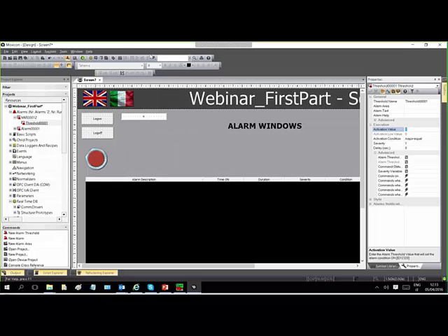The third way to generate the alarm, I'm using different colors to differentiate the ways. The last way could be, and sometimes customers are requiring, I have a new tag 17. I have an alarm that could be an alarm template, alarm 2, where I add just the activation minimum condition, activation value. Now I associate this alarm as a template, like I did before. Now, if I have this tag name, I can use this in the string table to give different descriptions.